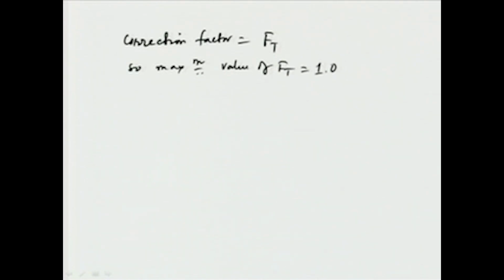Okay. And so the average LMTD is Ft into LMTD, or I should say the average LMTD is Ft into the LMTD actual, based on that configuration.